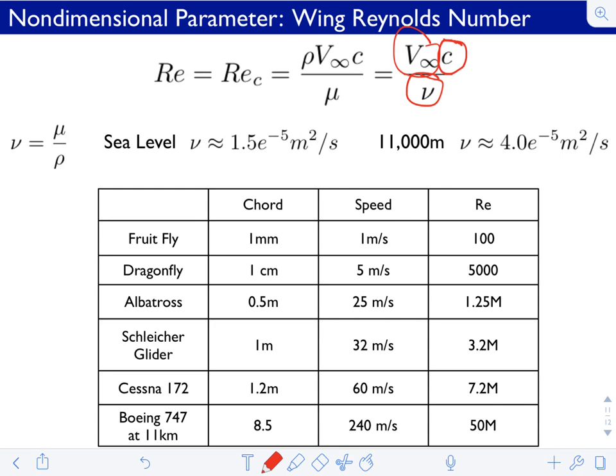Be cautious that unlike water, air has the opposite relationship. The viscosities have the opposite relationship with temperature. In the atmosphere, we have this variation, particularly in the density. The density is going to drop with altitude. And because nu is equal to mu over rho, and rho is dropping significantly with altitude, that means the kinematic viscosity is going to creep up. And there are significant differences.